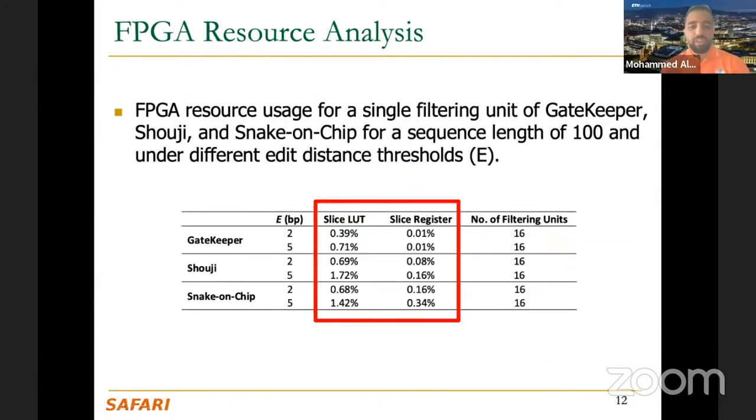So we implement this on GPU, FPGA, and CPU. And these are the results for FPGA resources. So this is the number of lookup tables needed. You can see most of the cases is less than 1 or less than 2% at most. And that is a very cheap algorithm to be implemented in FPGAs. And since it's very lightweight with a very low resource footprint, then you can use a large number of replications. So instead of solving a single problem, you can have 50 problems, for example, or 100 problems if the utilization is less than 1%.